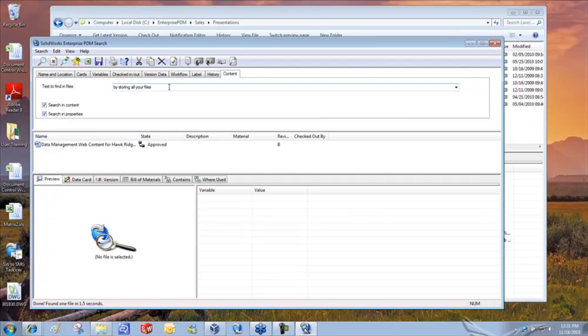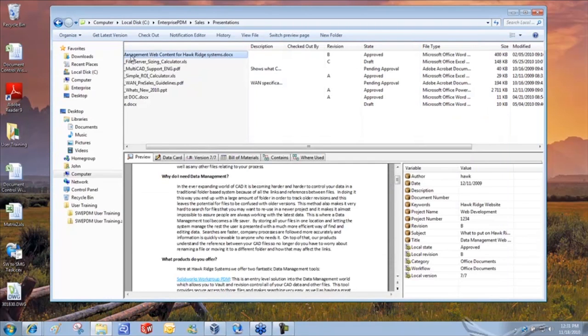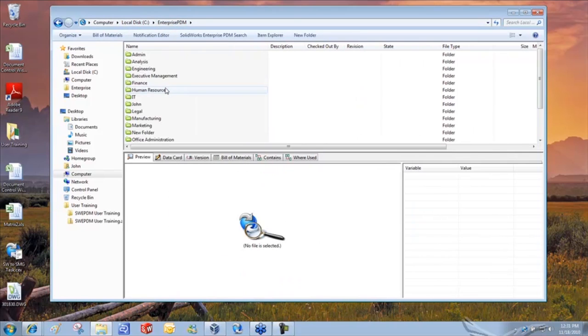When you install SOLIDWORKS, you actually get a SOLIDWORKS iFilter installed in the background, so you can index SOLIDWORKS content. If you have a SOLIDWORKS drawing, you could actually search for the notes that exist on that drawing.